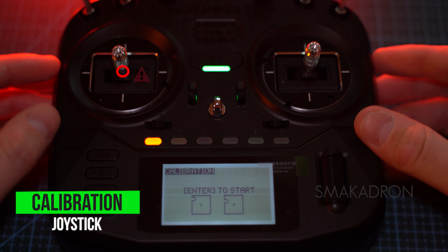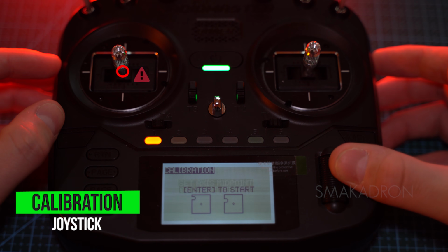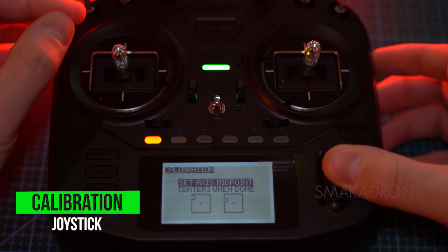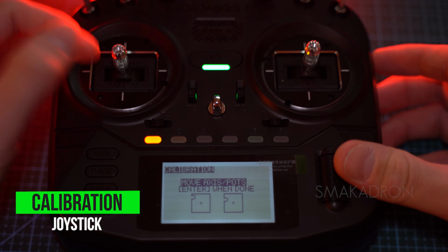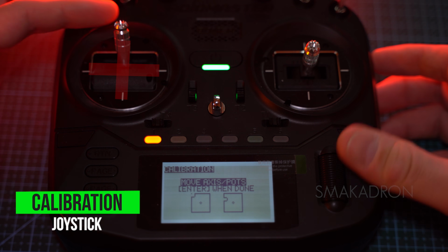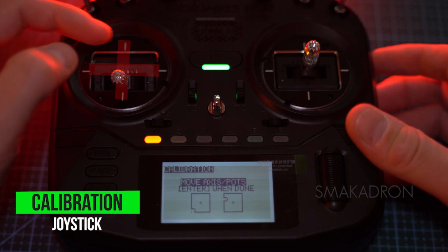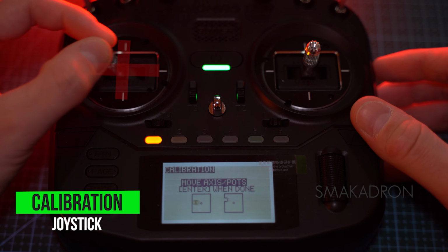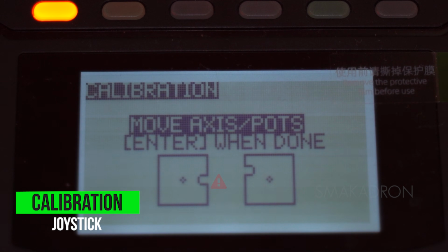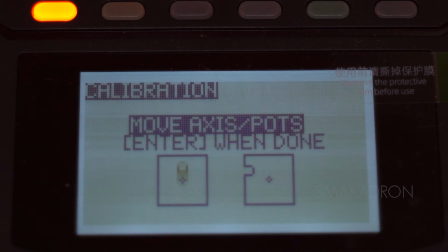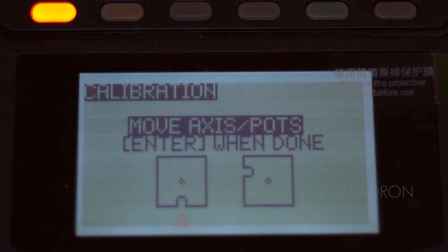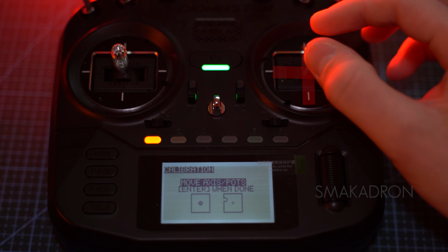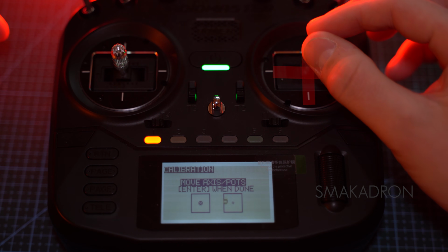We set the left stick on the screen exactly in the center as shown in the picture. Press Enter. We have no timer, so there's no need to rush. Let's start with the left stick. Calmly move it up to the point of slight resistance, and then down the same way. Pay attention to the stick square indicator. If the radio is working correctly, it should go past its outlines. Now, return the stick to the center point and do the same thing to the left and to the right. That's it. The left stick is calibrated. Do the same procedure for the right stick.